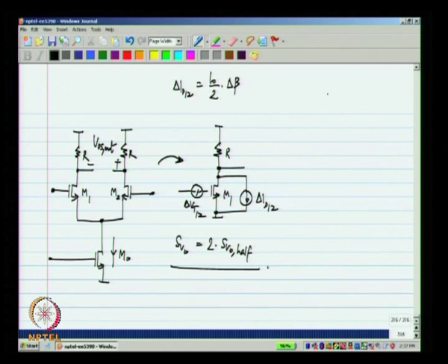or a voltage source. So, the mismatch current will be equal to the quiescent current flowing in the resistor, which is in this case I naught by 2. Let me assume this current is I naught times the mismatch in the resistance. Okay. Now, what will be given will be delta beta by beta and delta R by R and so on. For beta and R and so on, we specify the relative mismatch. From that we can calculate delta beta and delta R and multiply that by I naught by 2 here and there to get the equivalent current sources.